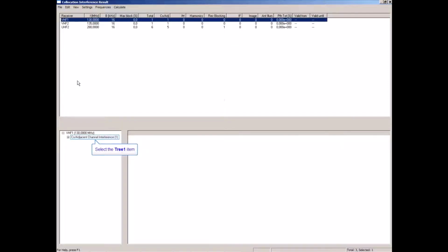what still is there. Yeah, we have some interfering cases. UHF1 that we started with is okay now. So what about this one? It is interfered with by UHF2. The amount of interference is about 5 dB. It has a margin minus 4.6 dB, and this is in effect the noise increase experienced by receiver VHF1 due to the interference from this transmitter.